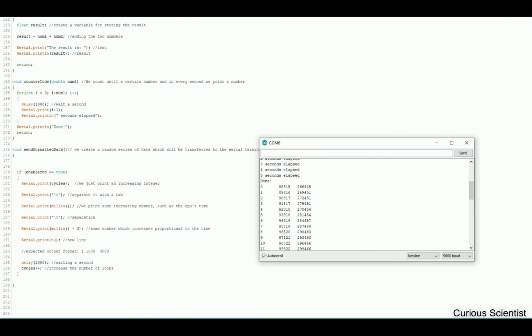And also you can make a string out of the several numbers and just send it by one serial.print command, which can speed up maybe, but I honestly don't know which process is quicker. If you send it like this, so you basically have to send 6 serial.print commands, or you have to merge the different variables into a string and just send the string by one command. We can make a test for that later, but I think this is the most important,